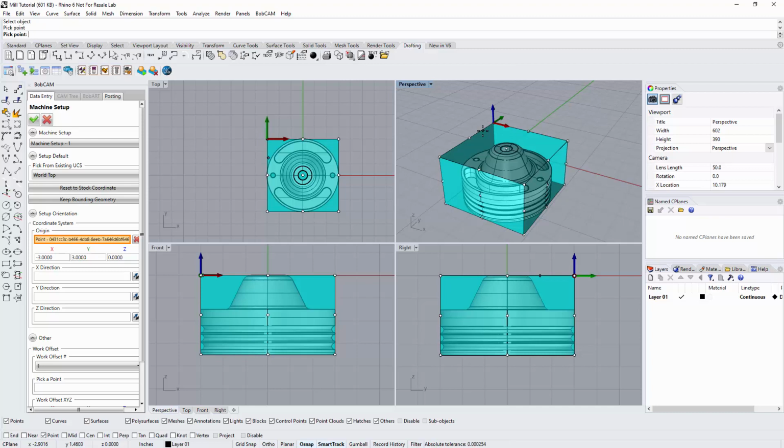Now, if I'm using this on a mill, I'm primarily going to be touching off the top of the part. So this surface that I'm zeroing from would be my zero location. If I was using maybe a router, maybe I'd pick this bottom left-hand corner here, and it would be at the bottom of the part because I'm zeroing off the spoil board on a router.